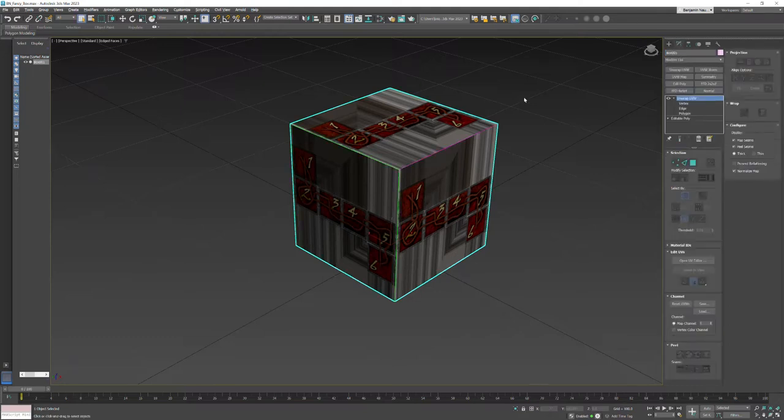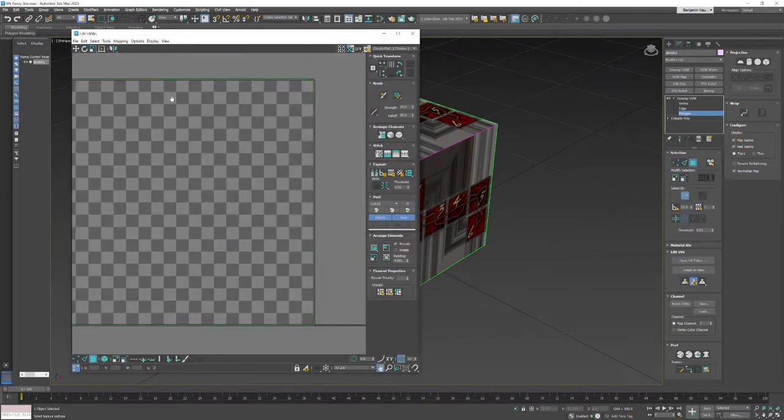And so this box already has some basic UV coordinates on it. As discussed in the lecture, we have X, Y, and Z, which is world coordinates, and then U, V, and W, which is our two-dimensional image coordinates. So I'm going to go to polygon, find the rollout for edit UVs, and click on open the UV editor.